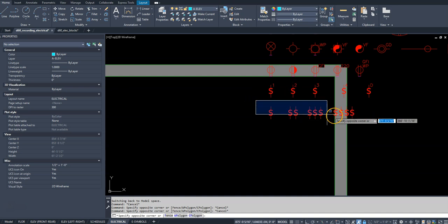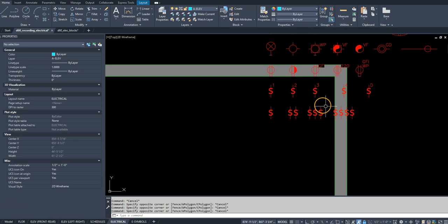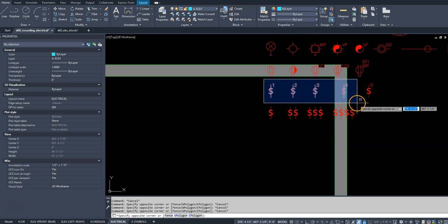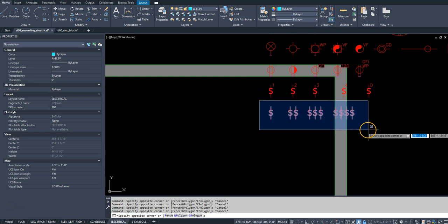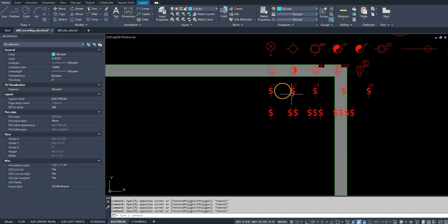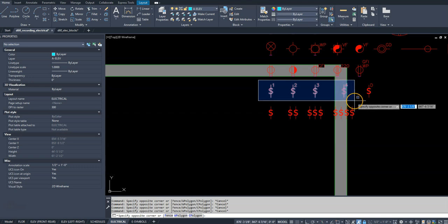The benefit of using these symbols as opposed to these symbols is that with these symbols you can show with your trace wire, your circuit trace, exactly which switch should be wired to which light. If you use these specific symbols, it's the electrician's job to determine which switch will be wired to which outlet and light.